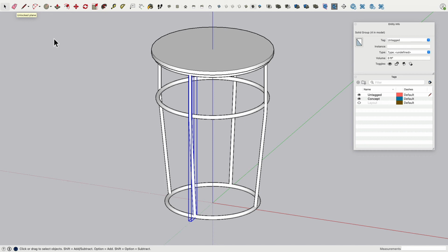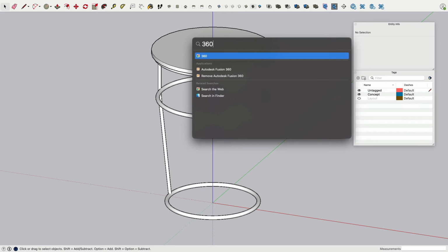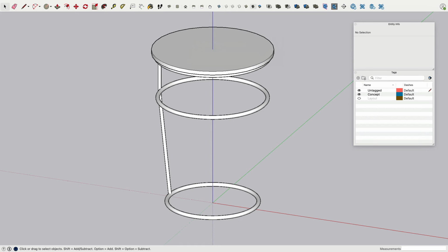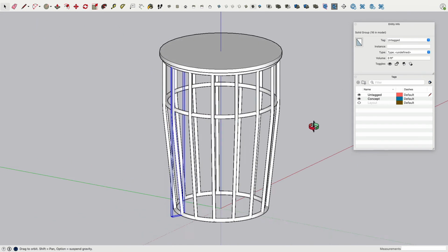But now instead of 4, we would like to actually have, let's say, 10 or so. So let's say we have 10. We need to divide 360 degrees divided by 10. That's 36 degrees. What about 15? 24 degrees. Cool. So check this out. We make a copy, rotate from here along. Now I type in 24, enter, and now I type in star to multiply and 15 and enter. Bang, done. Awesome, isn't it?